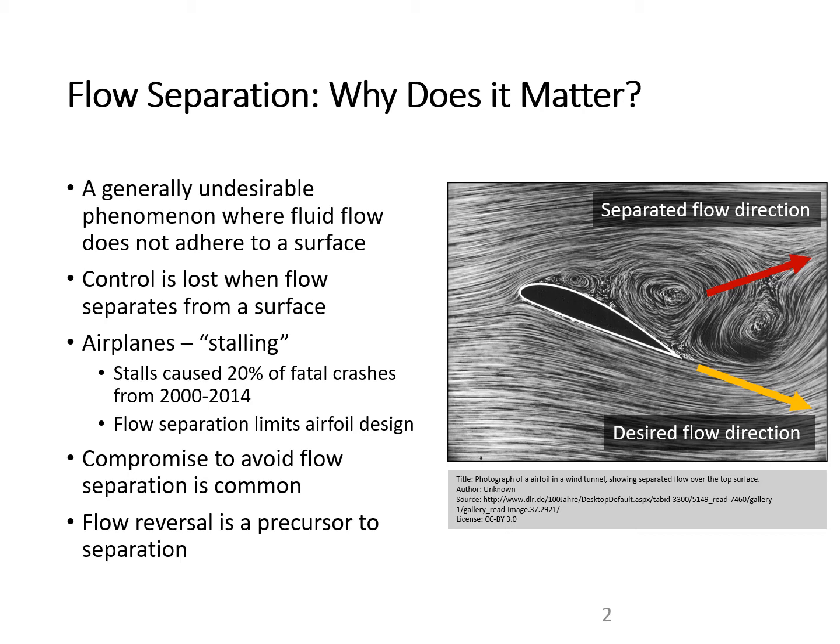In addition to this big impact on human life, flow separation also limits airfoil design. Really, in general, throughout fluids engineering, you see lots of compromises where performance is sacrificed because compromises have to be made to avoid flow separation. Now, flow reversal is the precursor to separation, and I'll talk about that on the next slide.